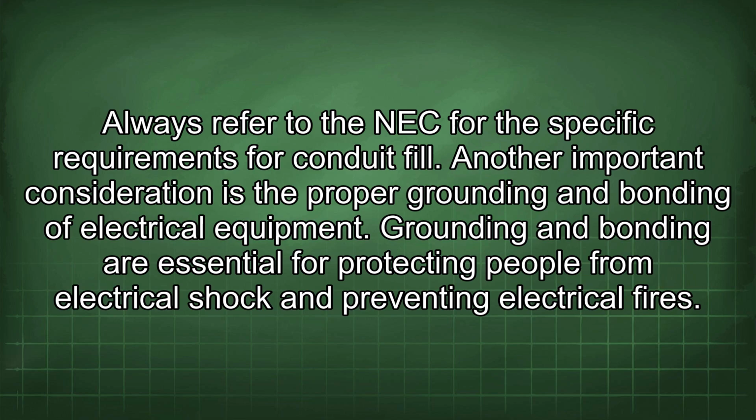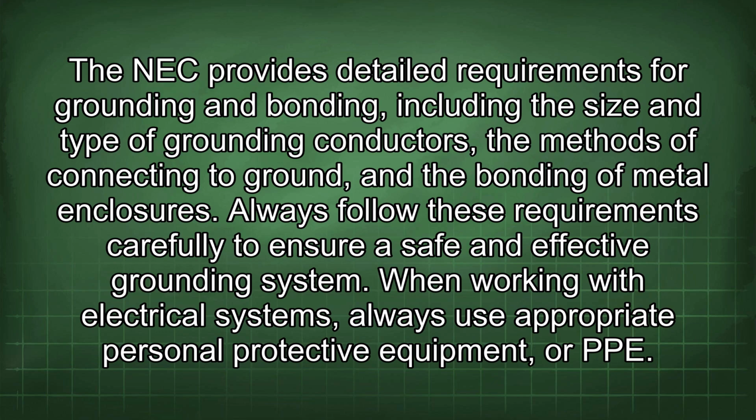Another important consideration is the proper grounding and bonding of electrical equipment. Grounding and bonding are essential for protecting people from electrical shock and preventing electrical fires. The NEC provides detailed requirements for grounding and bonding, including the size and type of grounding conductors, the methods of connecting to ground, and the bonding of metal enclosures. Always follow these requirements carefully to ensure a safe and effective grounding system.